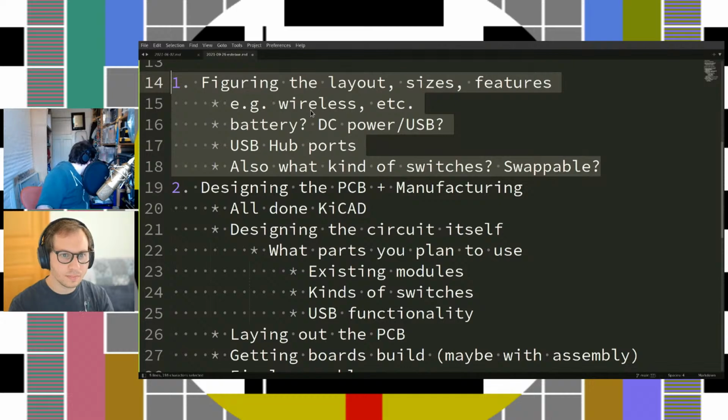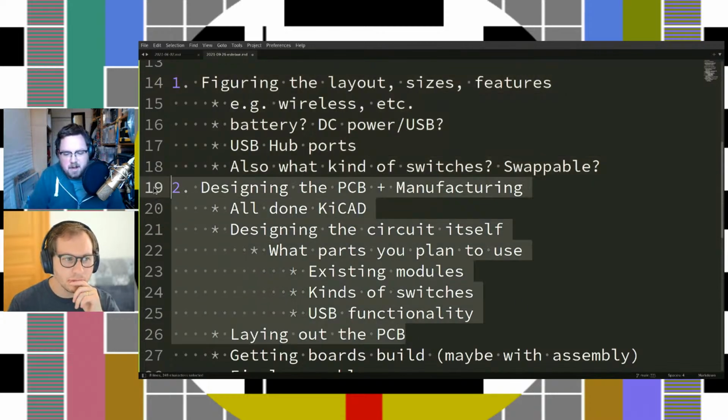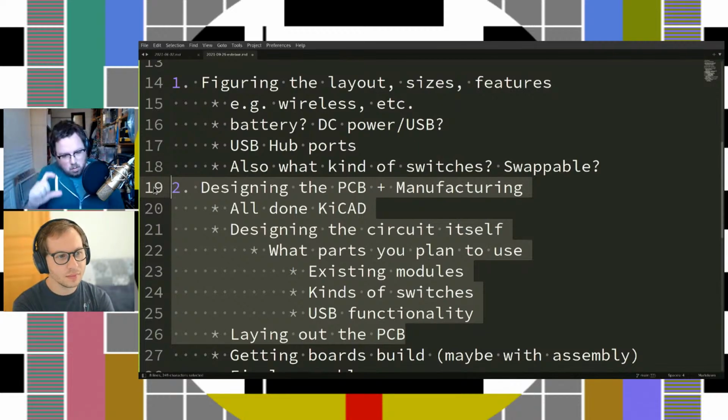What I did is I ended up following that for a while, and I picked 2 or 3 different kinds of switches, and then I just did one bulk buy of, okay, these are my low profile switches, and these are my big full size switches, and I use that for a bunch of different projects, so I just have them in stock. And that works really well with designing the PCB, because once you've verified this is my stamp for a key, when I'm doing my layout and stamping all the keys in where they go, I know that this will work because I've built 5 of these boards before, so I don't have to worry about double checking all the parts.